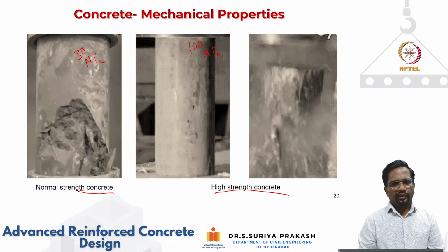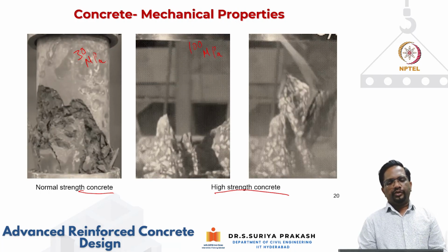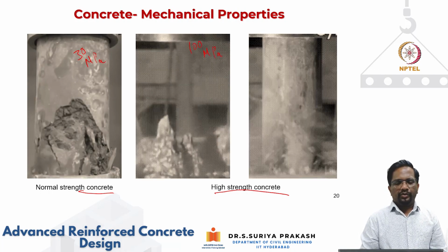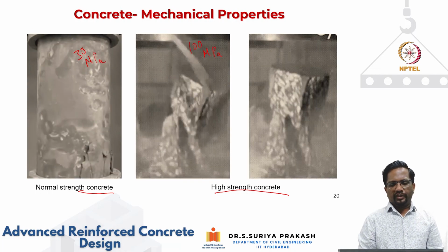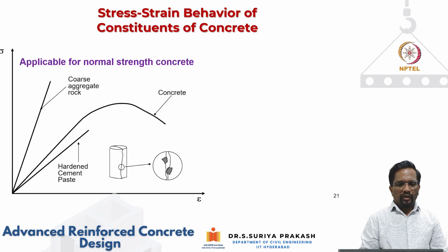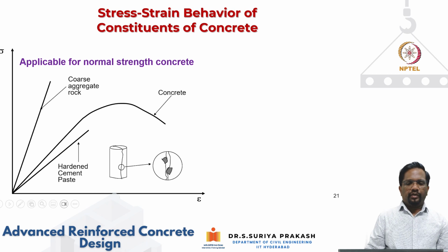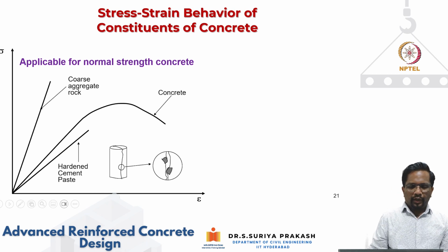If you're going for high strength concrete, it is always better to put some fibers that will give you a little bit of ductility. Again, the fiber dosage also has to be designed for. Right, so now let's look at the stress strain behavior of the constituents of this concrete.